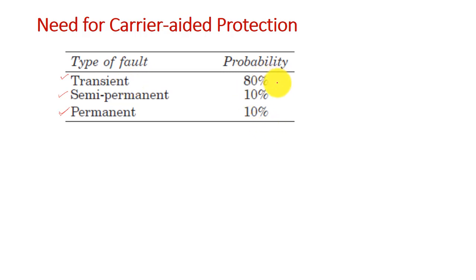In fact, this is tackled using the reclosure scheme in the protection methods. So there are reclosure approaches. As soon as the fault happens, the circuit breaker opens and recloses again just after a few milliseconds, right?